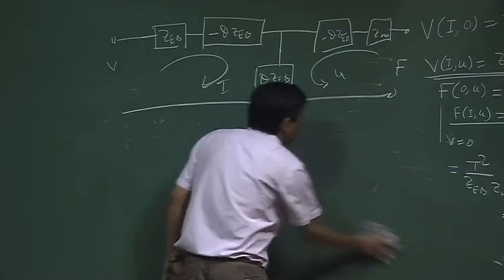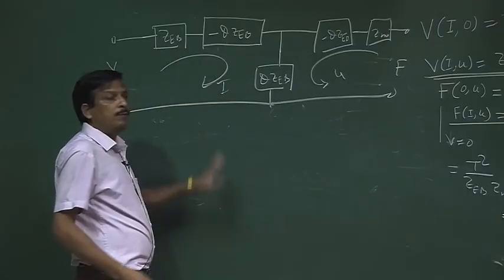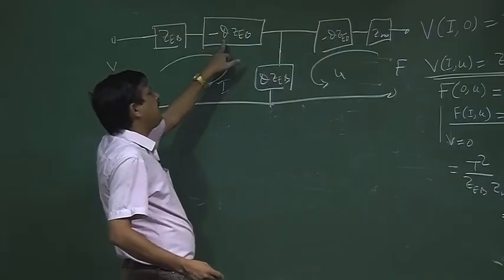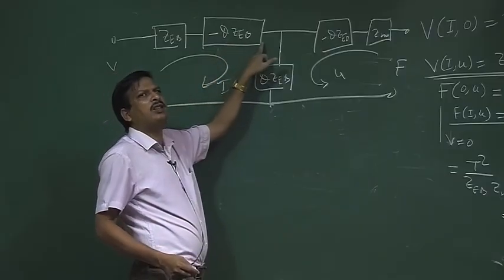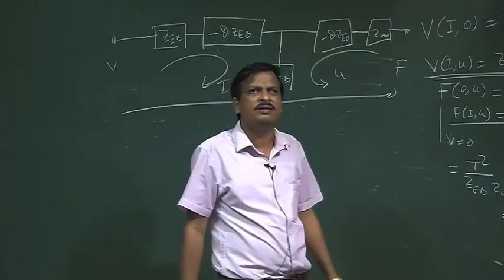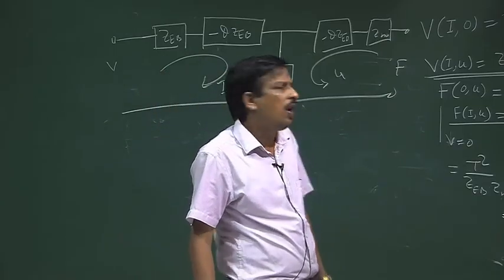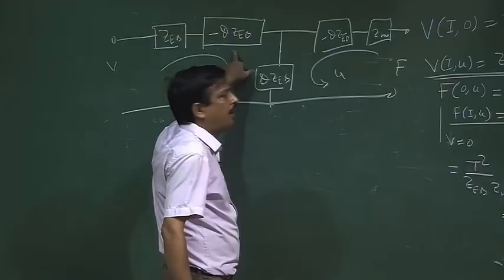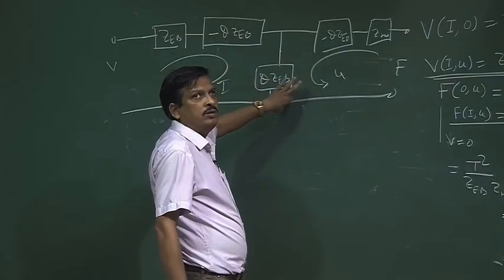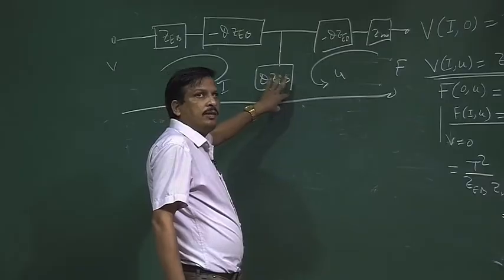So, the mechanical reciprocal transducer equivalent electrical circuit is this. Now, I cannot realize minus phi as a negative resistance. Can I realize a negative resistance? I cannot. So, how do I realize this negative part in the form of a coupling coefficient?